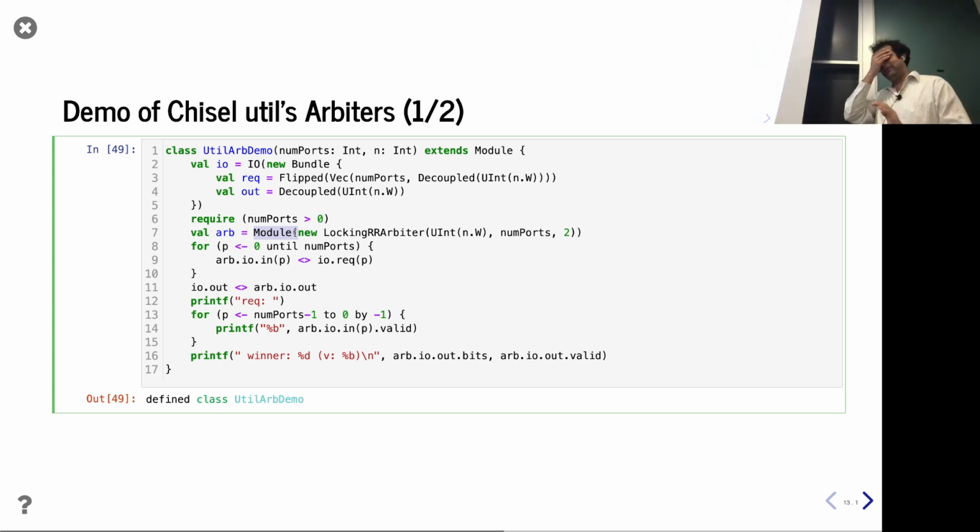I can't fully explain this. I vaguely remember about 8 or 9 years ago in Chisel 1, it may not have been this issue, but something similar. Scala had a method you could override that was guaranteed to run before any child class methods. We were using that, and we found out new versions of Scala were going to remove it, so they changed the language. That was about 9 years ago. Anyway, in this case, you have to wrap module instantiations like that. Even if you're not doing testing or not using a standard library, if you write a module and instantiate one of your modules in another module, you do need to wrap it. I'll admit that's not pretty boilerplate code. That's annoying.